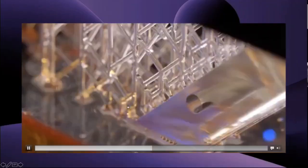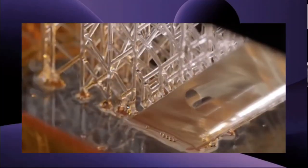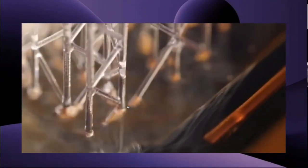The print is built in consecutive layers, each less than 100 microns thick. When a layer is complete, the part is peeled from the bottom of the tank, letting fresh resin flow beneath, and the platform is lowered once again.